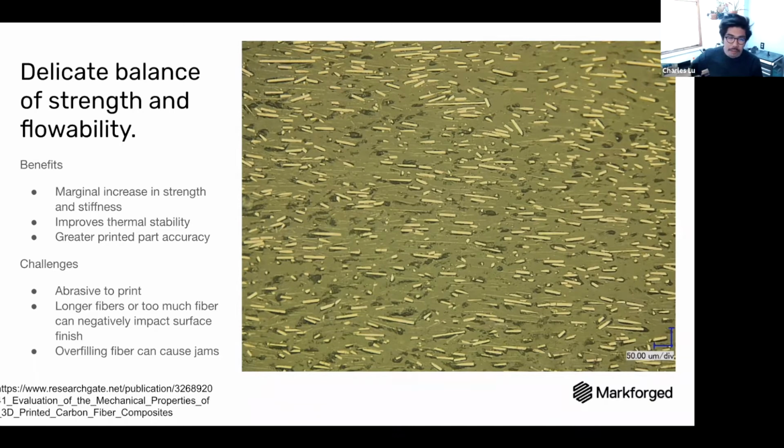And with Markforged, we obviously take care of that tuning for you, so you don't have to do anything. But the stability plus the increased stiffness means that you also have better bulk part accuracy. When we're talking about part accuracy, that involves the reduction of warp and rigidity, so that every single path of filament stays in place, and that results in better accuracy.